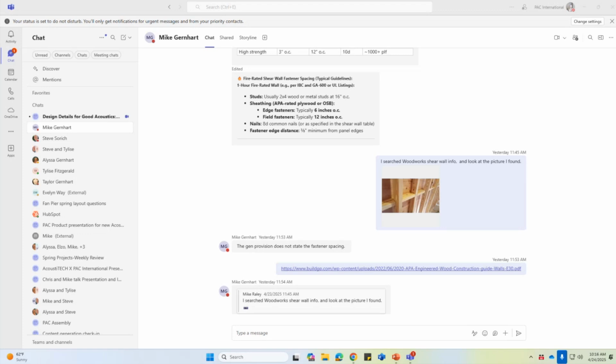So if you have a mineral wool wall that's an STC 54 and a fiberglass wall that's otherwise identical that's an STC 53, you can't say that those are different. Even if they're tested at the same lab, that's not a statistically significant difference in their STC ratings. Now, if you dig into the third octave band transmission loss data, maybe you'll see some bigger differences there that maybe are statistically significant.